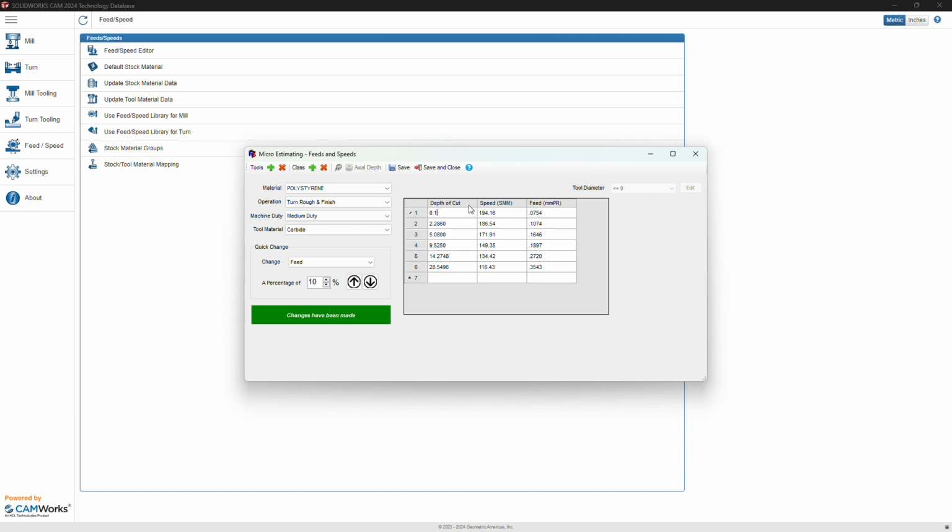When you go ahead and create a toolpath, you can always enter the feeds and speeds manually per toolpath. When you're using a bit and you set the feeds and speeds per the tool, you can always default to your tool. But to really get the most out of SolidWorks CAM, you do want to spend a lot of time setting up your feeds and speeds based on your material, so that it will automatically generate these for you, or really, so that you don't accidentally use a default feeds and speeds which is way off from what the Carvera should be.